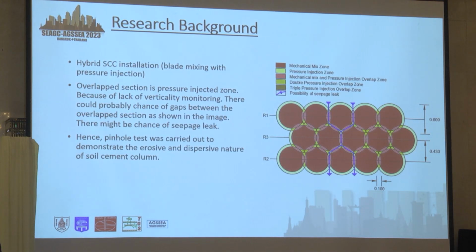So this is the plan view of the soil cement column that was carried out in the crest zone of the dam, showing the overlapping sections of the soil cement columns. After the dispersive soil was found, the question arose whether the cement would improve the quality of the soil and its erosivity characteristics.